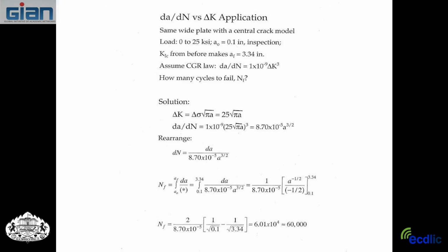And if people want to do that analysis, 60,000 takeoff landings is pretty many. So that's not bad. If you do this analysis and get a number, I wouldn't rely on it exactly to the number. I'd say if you're predicting a life of about 60,000 cycles, maybe it's good for 6 to 10,000, and then you might want to do it over again, do inspection or something.